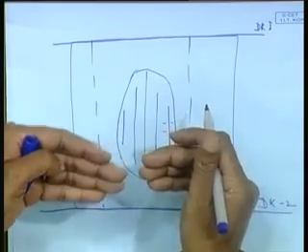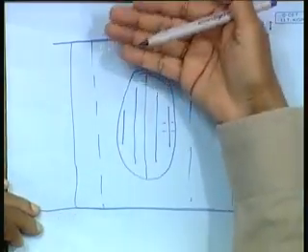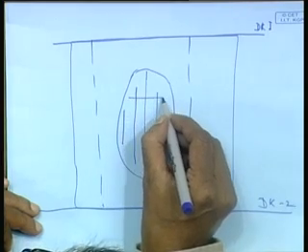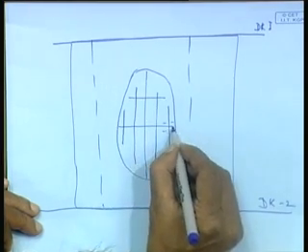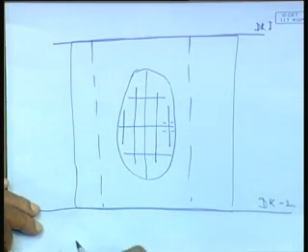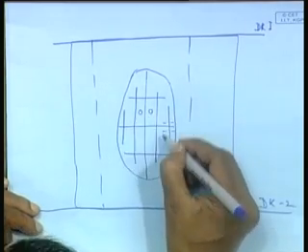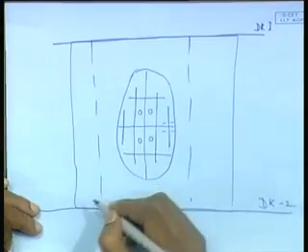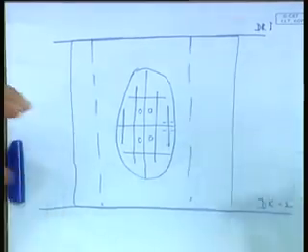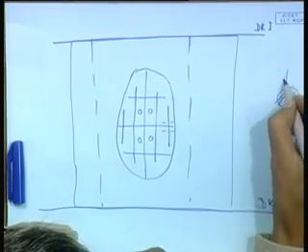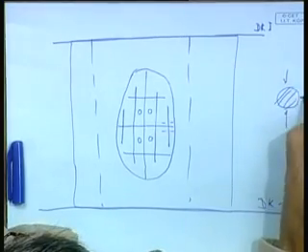Similarly, it has a bulge in this direction also, so you may need to give certain heating lines like this. In addition to that, spot heating, because in spots it is shrinking from all directions. If you are heating a circular zone, it will shrink from all directions.